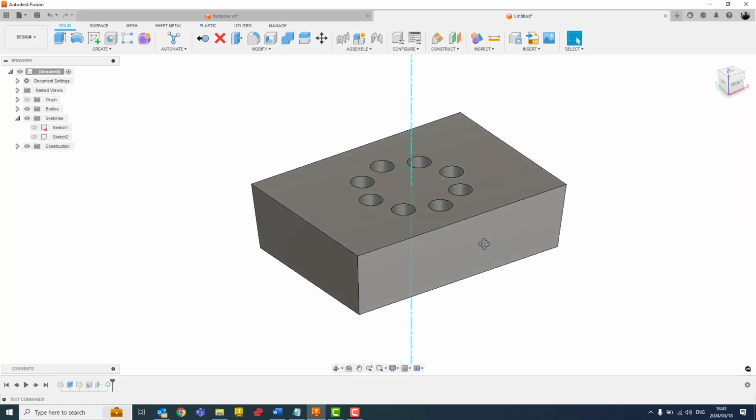So now you can see I've used a couple of different parameters: user with millimeters, as well as user with the unitless tag. And when I was creating my parameter, I said height equals so and so. It actually assigned it as a favorite as well, because I was not going through the parameter dialog box, but through the dimension dialog box.